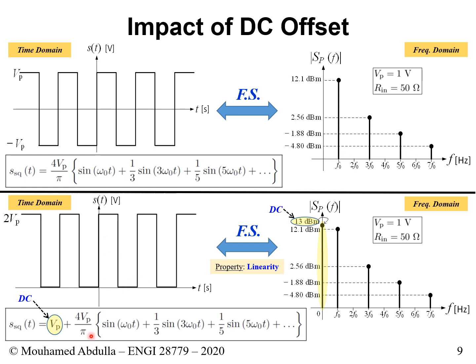So we see the DC component in the equation, we simply add it. We see the DC component in the frequency domain, we simply add a spike at frequency 0. And you need to figure out what this value is. Now, this value, you have to be careful. It is not like what we did before. This is a DC component.